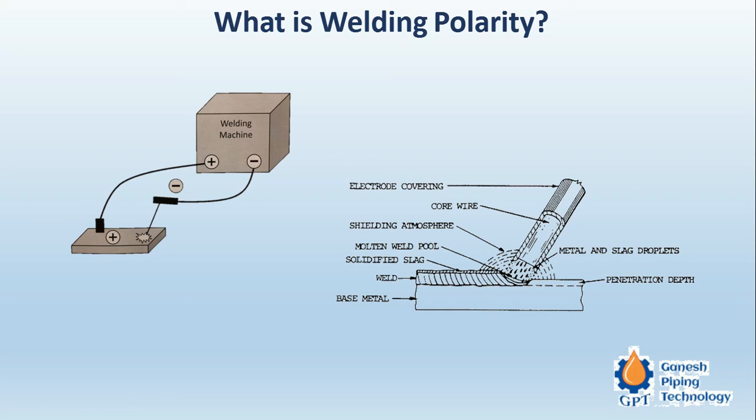So in that case 85 to 90% of the metal will be deposited from the filler metal, and the 10 to 15% fusion will take place on the parent metal. That is, the two dissimilar plates will also fuse by 10 to 15%. So that is why we will get a homogenized joint and it will be strong enough.